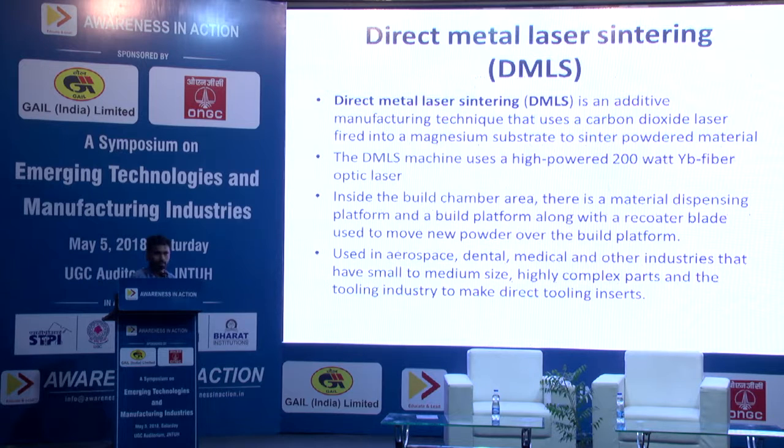Basically, the support structure cannot be removed using any cutting plier or manually by hand. This needs a proper machining process, because again we are talking about metal over here, so we cannot remove it manually. And even the slicing process for DMLS is totally different, because the powders are very costly, and the machines currently available in the market start from 2.5 crore. So currently in India only defense industries are going for this technology, because I think small SMEs cannot afford a DMLS process.